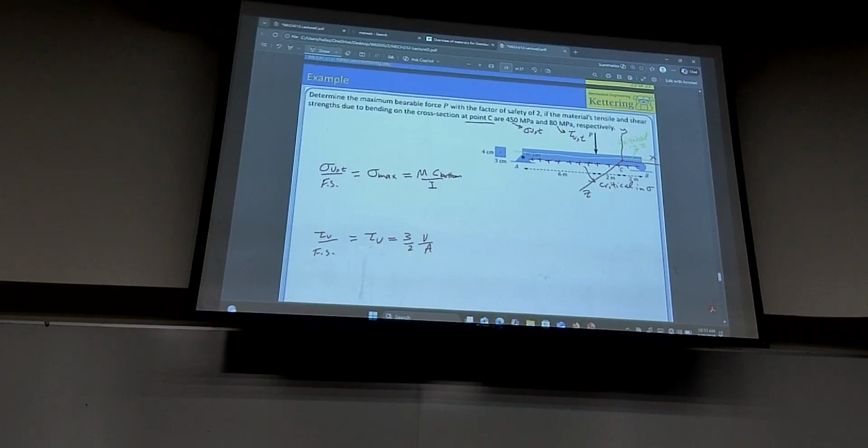Now, the bending, we think, is about which axis? It is around the Z. Yes, very good. So could you let everybody know what you did? That was correct. What did you do to figure out that Z? I just kind of visualized it and bent it down and said, all right, it's kind of looking like it's going around the Z. That's it. The approach is exactly that. We exaggerated the deformation as you said, and see it curves around which axis. So write it down. To figure out which axis, ask this question: it curves around which axis?